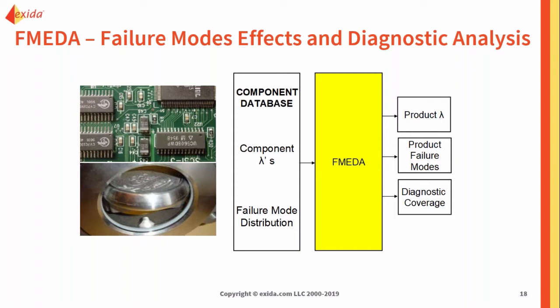One negative thing with the FMEDA is you have to be considerate of what the component database is for the FMEDA. With the component database, just like we explained earlier, if you're using bad numbers to go into the technique, you're going to get junk coming out of the technique as well.